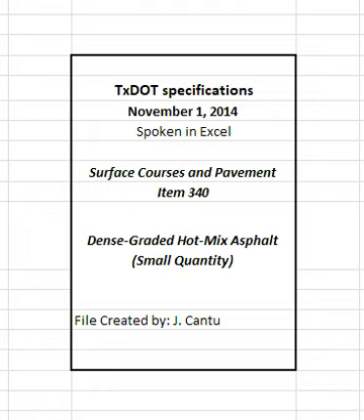2.1.1.1 Blending Class A and Class B aggregates. Class B aggregate meeting all other requirements in the table may first be blended with a Class A aggregate to meet requirements for Class A materials. Ensure that at least 50% by weight, or volume if required, of the material retained on the number 4 sieve comes from the Class A aggregate source when blending Class A and B aggregates to meet a Class A requirement. Blend by volume if the bulk specific gravities of the Class A and B aggregates differ by more than 0.300.